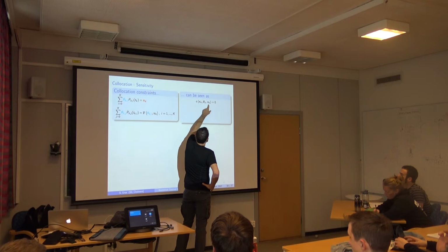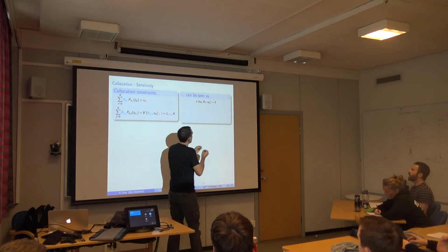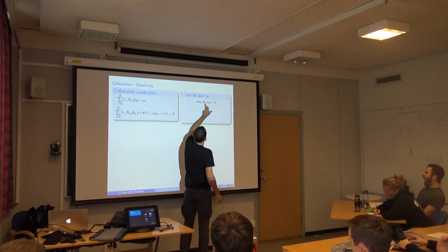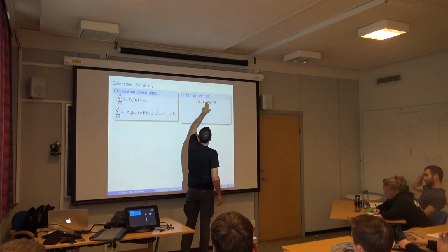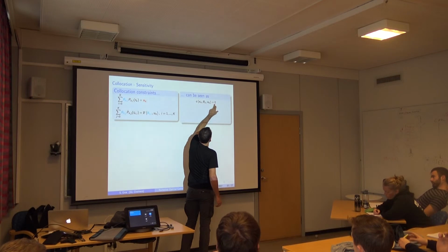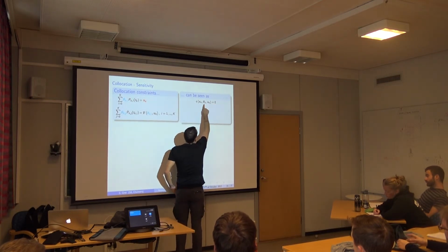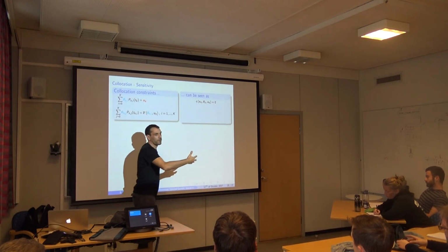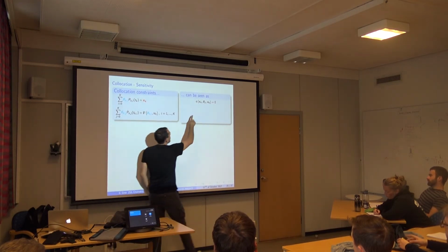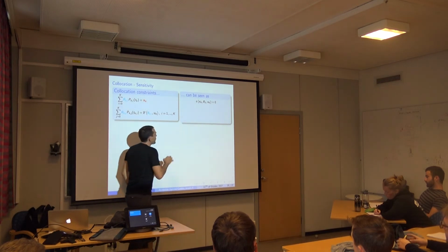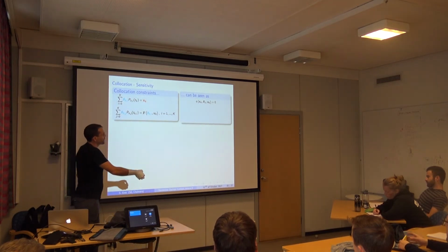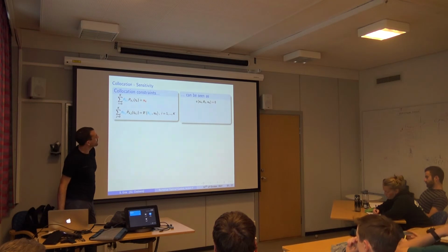You provide xk uk and you have to solve them, for example, via Newton to give you theta k. And in that sense, you should view theta k as a function of xk uk, because theta k is always adapted such that this holds. So if you were to change xk in these equations, you would need to change theta k accordingly, for this to always be satisfied. So in that sense, theta k is an implicit function of xk uk through this set of constraints.